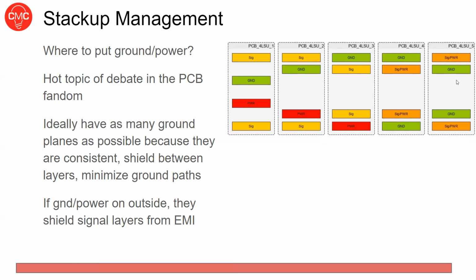But if you're having something more like, okay, the really noisy power converter here is causing this really sensitive gigabit Ethernet line to screw up sometimes, then maybe you're going to want to put ground planes in the middle to shield them from each other and put those on opposite layers. So just some different things to consider. And then you can do the same thing with power and ground planes.